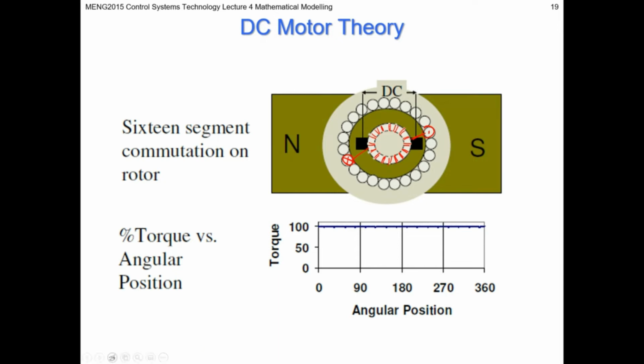Then in a second, as the motor rotates, you're applying current through wires that are in their maximum torque zone, right? But in a short while, you're going to rotate around, and then you want to apply current and torque instead to, say, this one and this one.